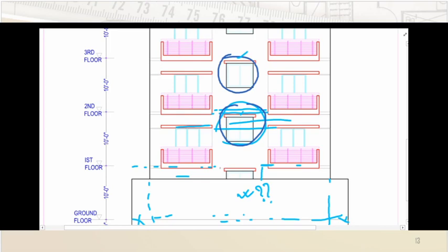This thickness of the sunshade will be not more than 6 inch, better if it is 4 inch. However, there will be some extension beyond the window for this sunshade, say not more than 1 inch, better 0.5 inch each.